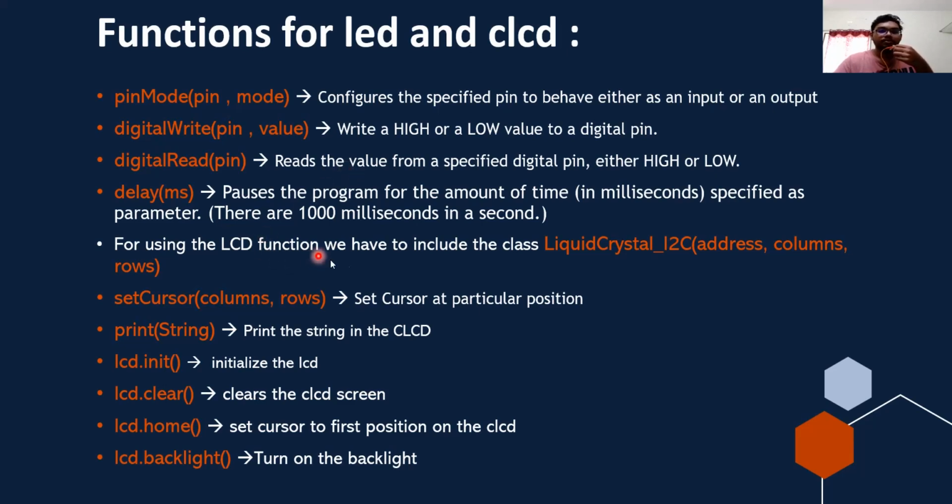For the use of LCD functions, you have to include LiquidCrystal I2C. This is the library you first have to include to use the LCD, and then you will initialize the LCD by lcd.init, and then you have to turn on the backlight, which is lcd.backlight. lcd.clear is used to clear the screen, and lcd.home will set the cursor to the first point. It's like resetting everything.